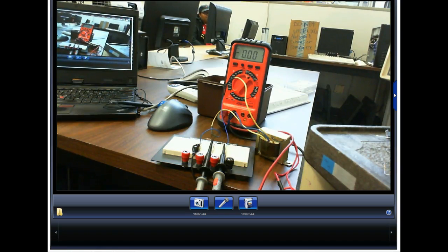Well, that's obvious. You're right, Scott. It's set on DC. So I've got my meter on DC, and so it's giving me the DC average of a cycle. What's the DC average of a cycle? 0. We'll see how many get this. This is a small class, and it's on the first test, and somebody's going to miss that in this class. I've never taught a class where somebody doesn't get that wrong.